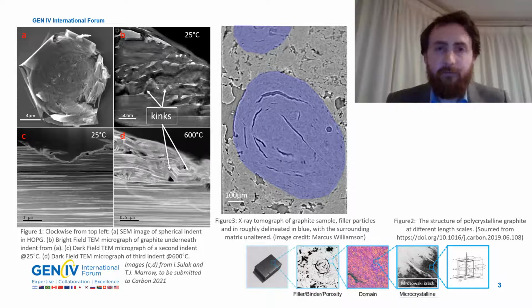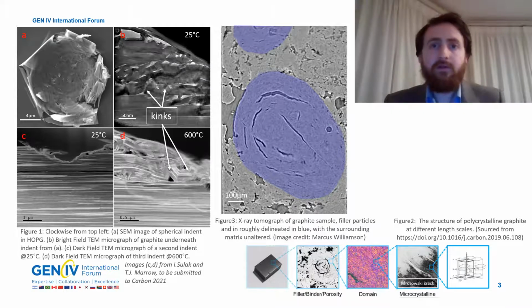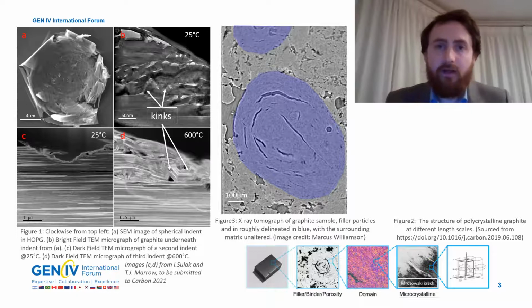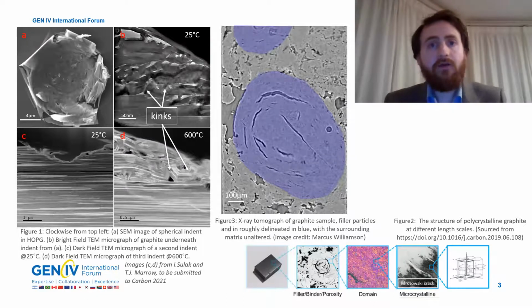D at high temperature. I will use high temperature spherical nanoindentation on an ion-irradiated pyrolytic graphite and combine that with cross-sectional TEM imaging. This will allow us to relate the observations of the graphite deformation in the electron microscope to the measurements in the modulus made by the nanoindenter. We will be able to understand for the first time the effect of irradiation as well as temperature on this kinking mechanism.